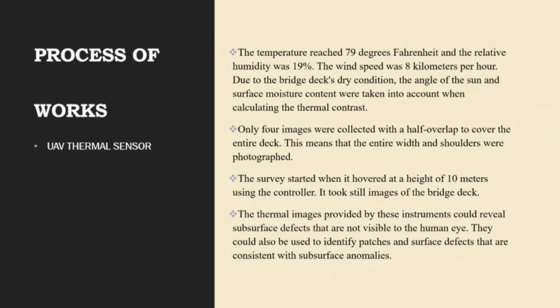The survey started when it hovered at a height of 10 meters, and the thermal images provided by this instrument could reveal subsurface defects that are not visible to the human eye. They could also be used to identify patches and surface defects that are consistent with subsurface anomalies.